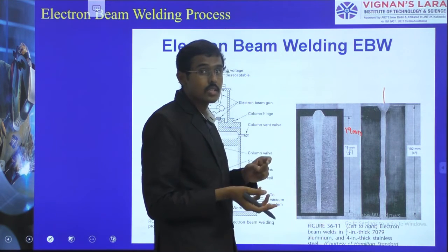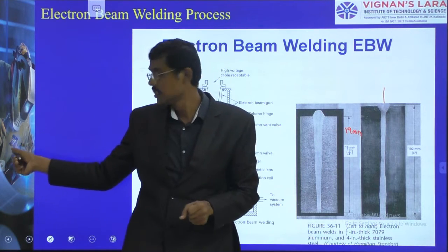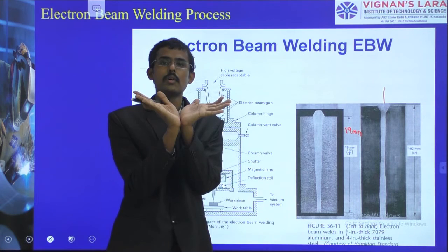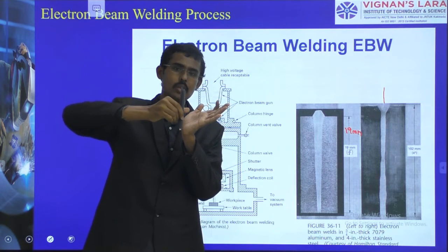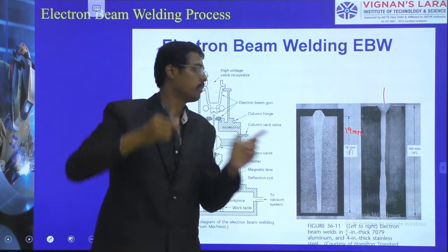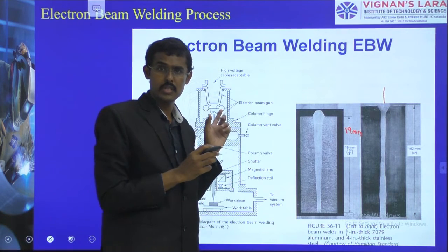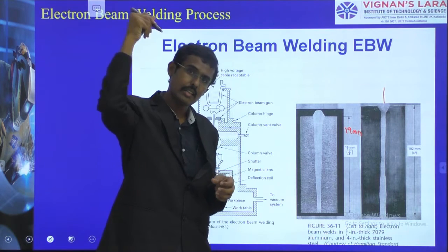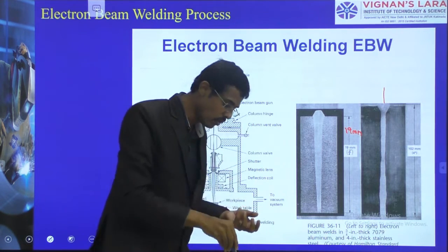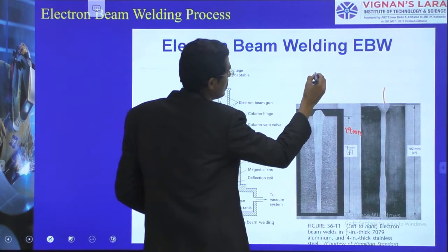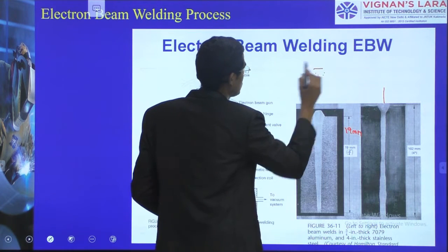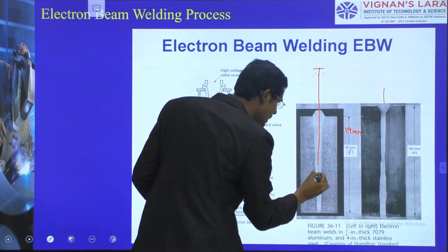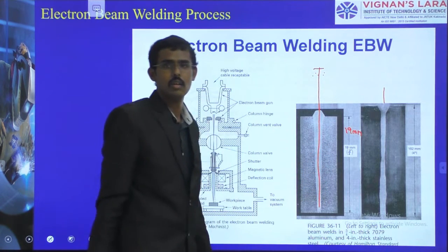For this large thickness, in electrode welding or submerged arc welding, we would have to prepare a large V gap, come down to 0 mm at the root, and then do welding. But here, with electrons at 70% of the speed of light, we are supplying high kinetic energy. The electrons with heat come down and impinge from there. It is a setup of an electron-releasing tungsten source, and the electrons come down and hit all the way through with heat at high speed, and it is joining there.